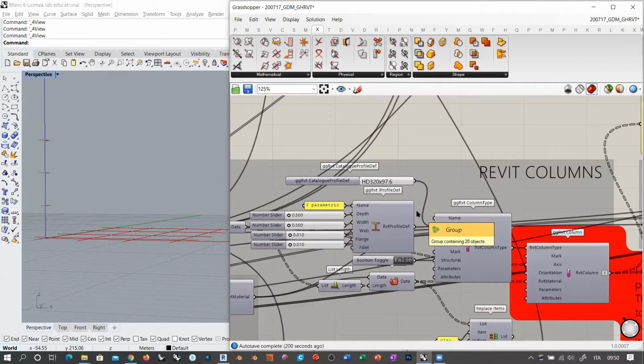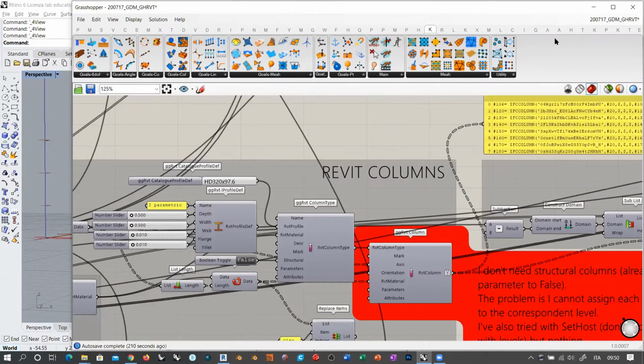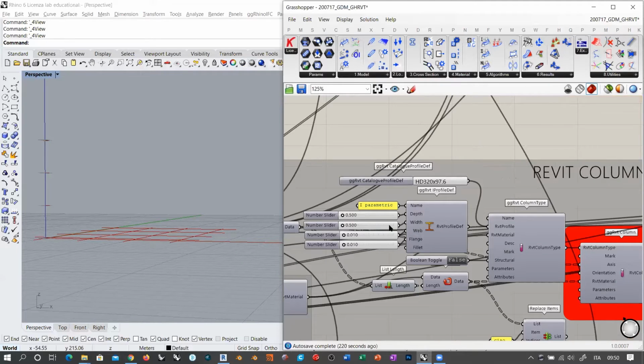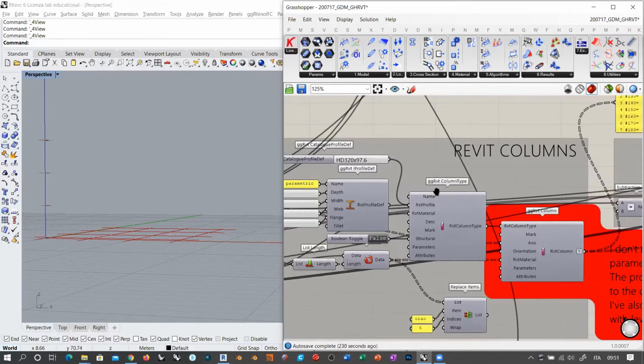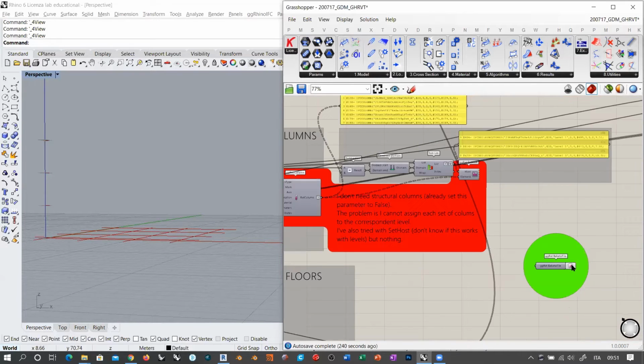I don't know if you're familiar with this, but you can use some optimization processes in Grasshopper to connect it to some structural plugin, like for example, Karamba 3D, which is around here, is one of the keys that we have. Yeah, this one. So in this case, for example, you can run this optimization by optimizing the various parameters of this section in order for this structure to work, basically. And once you run the optimization, then you can export to Revit. So you will have also a pre-calculation made on the structure that you are exporting.